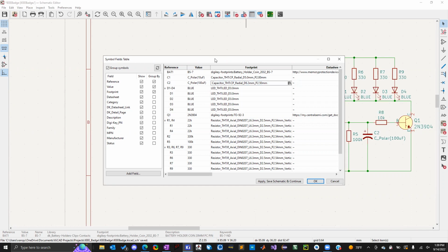Every pin is going to be extremely close to each other. And it's possible that the manufacturer can't do that. So if you send in that board, they're either going to deny you or it's not going to come out with as good quality because you didn't follow the rules of what the manufacturer said they could handle. And I'll go over a bit on how to configure that once we move on from this step.